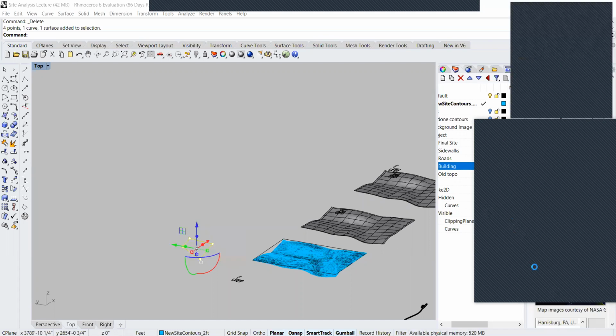Someone asked in the chat if there's a way to use Grasshopper to edit the contour lines or topography. Grasshopper works on its own merit within Rhino. So yes, you can computationally change the topography. Grasshopper likes points and curves, so it will get you as far as designing the topography that you want. Then you just use the same commands of extract point and patch to create it.